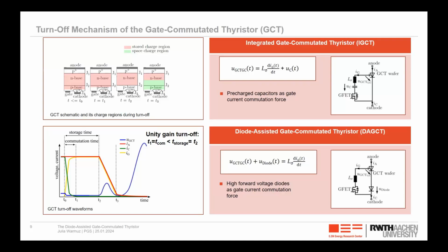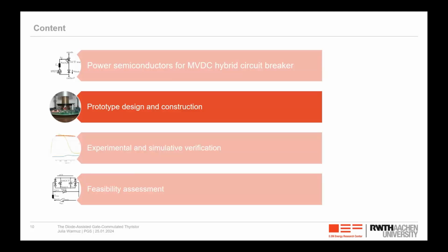I will talk about this later, but here the diodes have the advantage that the voltage is just dependent on its conduction current, and we can design the driver way easier with a lower stray inductance, and we can have higher voltages here for the diodes. So for the theory, let's see how the prototype could have all these features that I just promised.